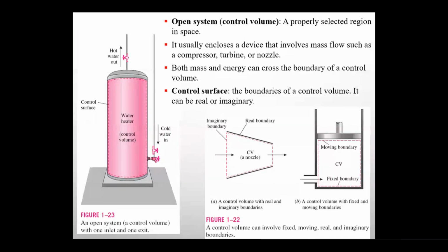You can still have it as a control mass, a closed system, such that you have all the pipelines enclosed within the system. The geyser, both hot and cold pipelines, and the tank all within the system. So you have all the components within the system. You can have that as a closed system. The mass is all circulating inside it. But that would make your problem much more complicated to analyze. So the way you define your system defines the complexity of your analysis. Clear? The easiest thing was to take it as a control volume.